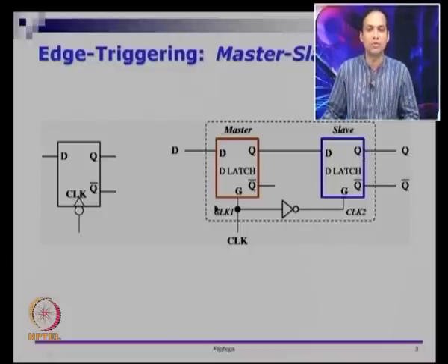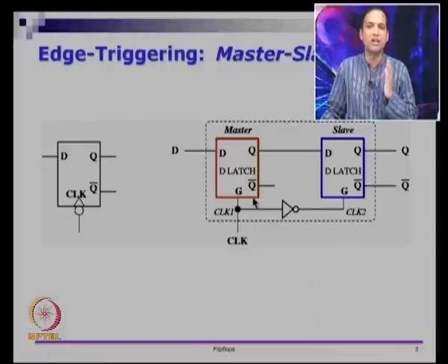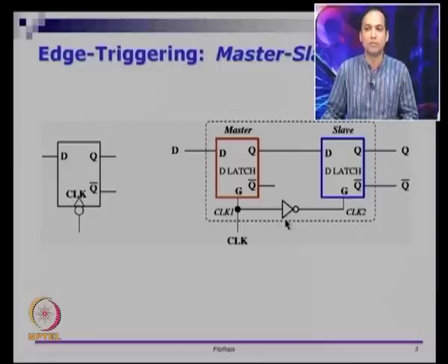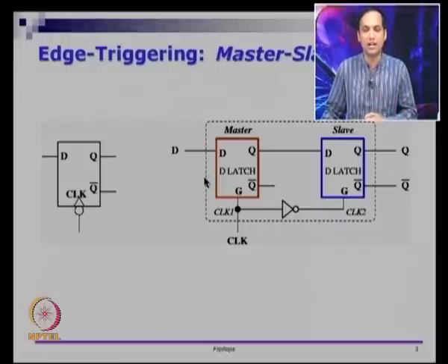The best way to think about that is to think of it as a black box first. It is taking two inputs and giving two outputs, and there are some interesting internal connections of the latches that we have made to get you the D flip-flop. So, this is called a master-slave D flip-flop. Specifically, this circuit becomes what is called an edge triggered circuit.